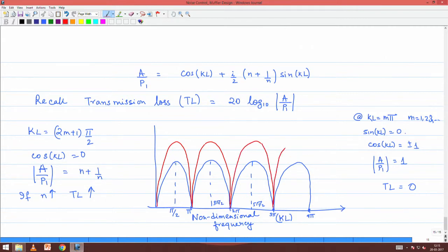You will have more transmission loss if you introduce a further high change of cross sectional area. So, in my drawing, in red I would have plotted for N2 and in blue I would have plotted for N1, and N1 is less than N2, right. So, if you introduce large cross sectional change, you will get larger peak values of transmission loss, but the nature of this curve will look exactly like this, right. So, this is the transmission loss versus frequency curve.